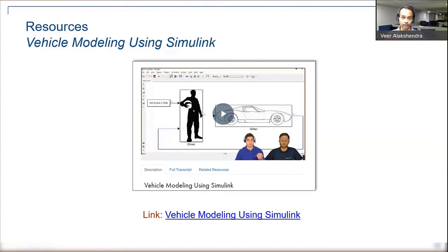So, moving ahead. There was a question about how the XY coordinates of a track are incorporated for doing a closed loop simulation. This is what we are going to answer. To answer that, the plant, which in the previous case was the longitudinal vehicle dynamics, now has to also include the lateral vehicle dynamics.